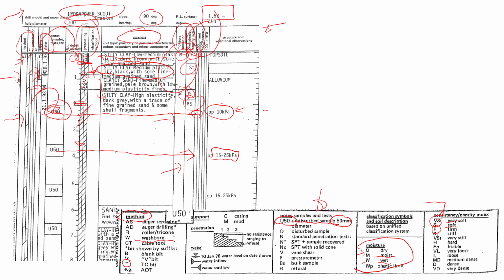Another piece of information, it's not very common to see this one, because sometimes we have different information that we can put in the borehole logs. This one actually tells you about the origin of the soil, which I found very, very helpful because it tells you what material it is and how it originated, and that correlates really well with the properties. So here we will see topsoil, and you see this topsoil is kind of firm, which makes sense.